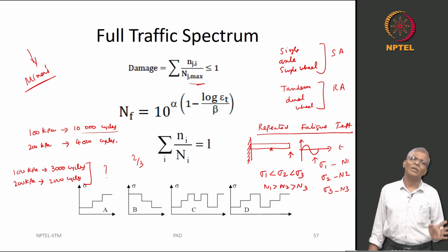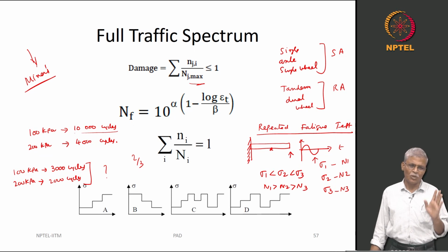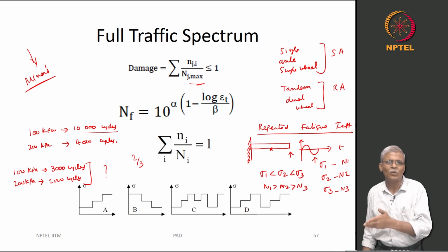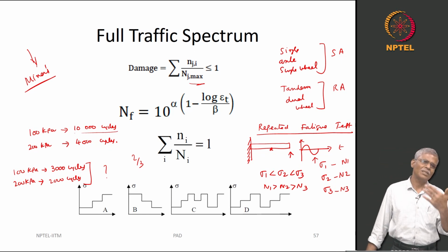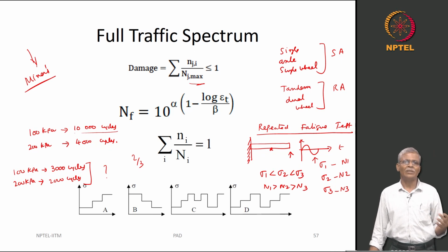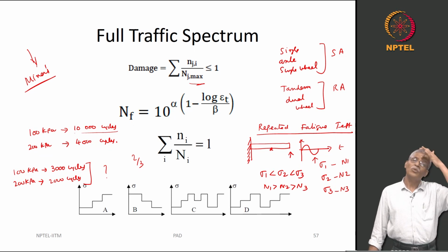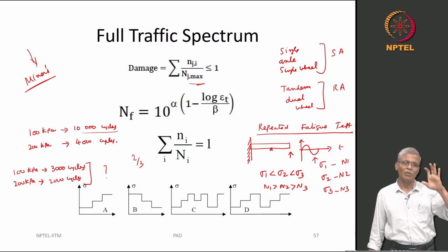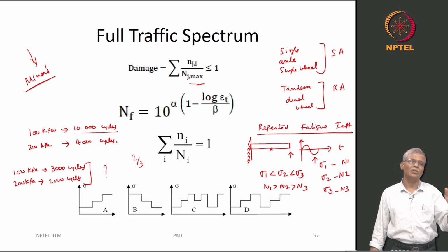What is the idea behind this Miner's fatigue? You are basically saying that the successive loading intensity does not necessarily damage the remaining load carrying capacity of the material. So, that means as if you assume that the material has the same structural constitution, it is not changing.